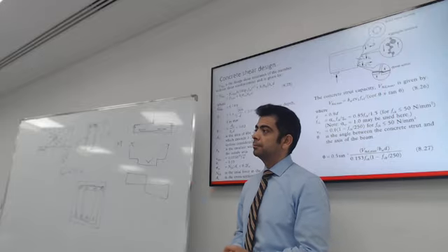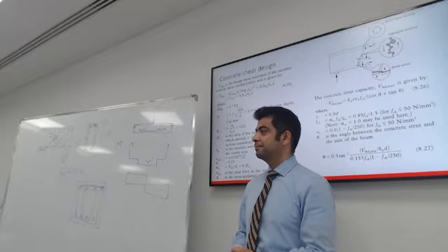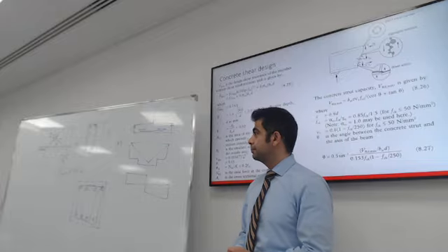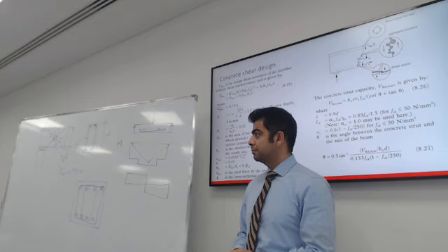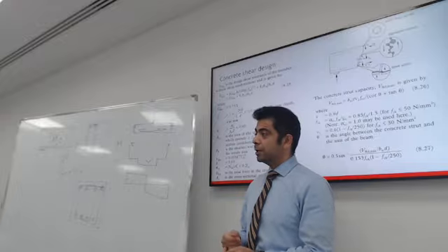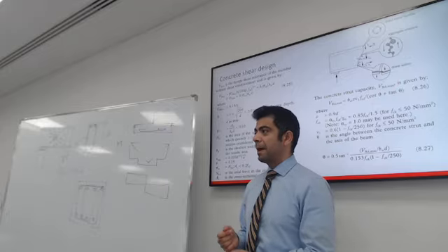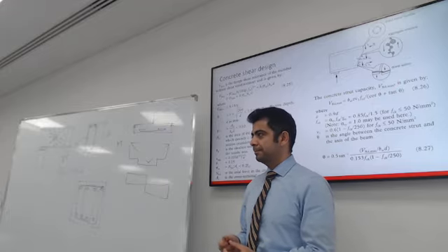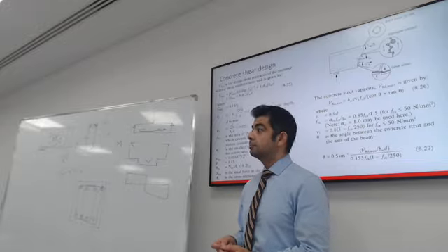Yeah, I get it. But didn't we say that the ratio of steel and concrete has to be within a maximum so that failure doesn't become brittle? Yes, you're right. Brittle, yes. So make sure you don't exceed the maximum reinforcement ratio. So we have to do a check at that first?